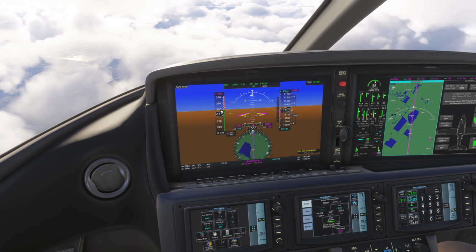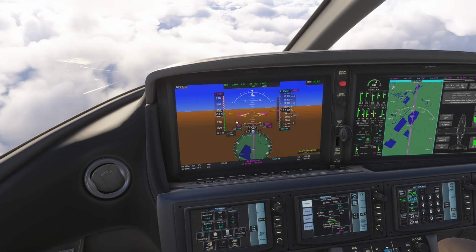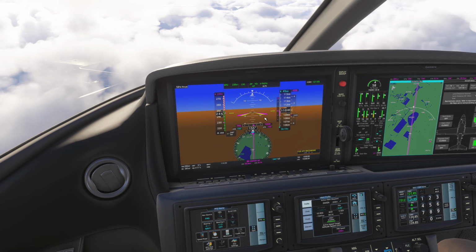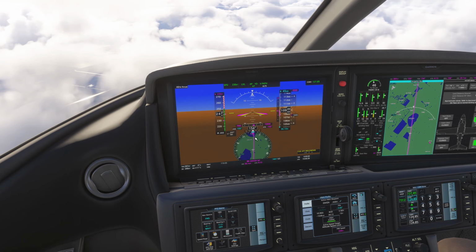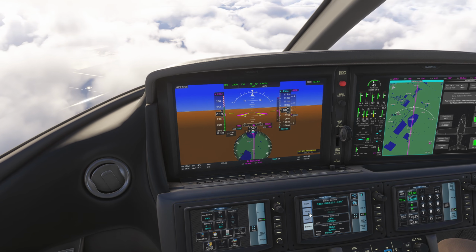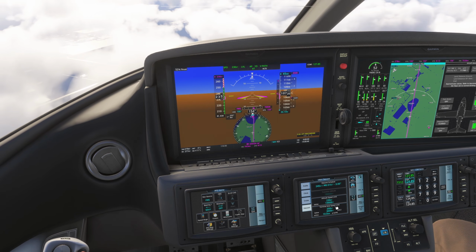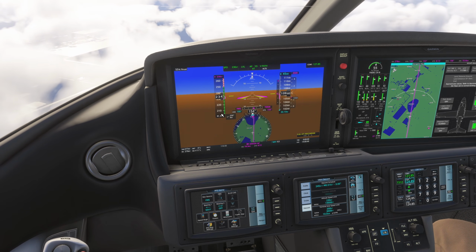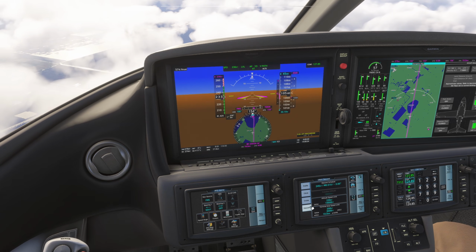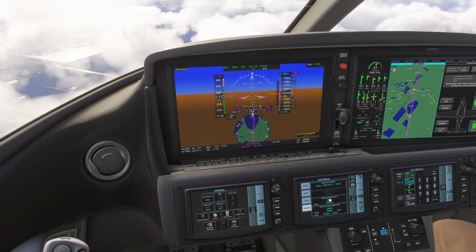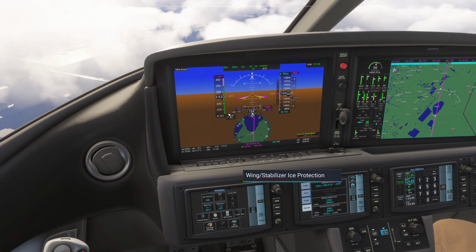Just at the border of the 250 knots constraint, remember, below 10,000 feet we cannot go above 250 knots. Look, it started to slow down to 230. And that's a new speed limit below 10,000 feet that I set. And the plane is now starting to target it. This adjustable VNav is very useful when you're in career mode. You do not want to go over the speeds.